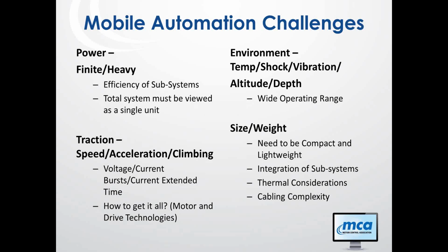I touched on this a little bit before with the slide. It talks about power. We're always going to be worrying about this power. Batteries are heavy, they're finite, so how can we enable that charge or that potential energy that it carries? How can we make the bot operate as long as possible with that finite charge? So we're going to look at efficiency of the subsystems, and you really have to look at the whole system as one. We can't look at each subcomponent individually. We run into many applications where an engineer will design a very efficient motor, and to run that motor we have to add inductors in front of it, and there you really kind of shot that efficiency.